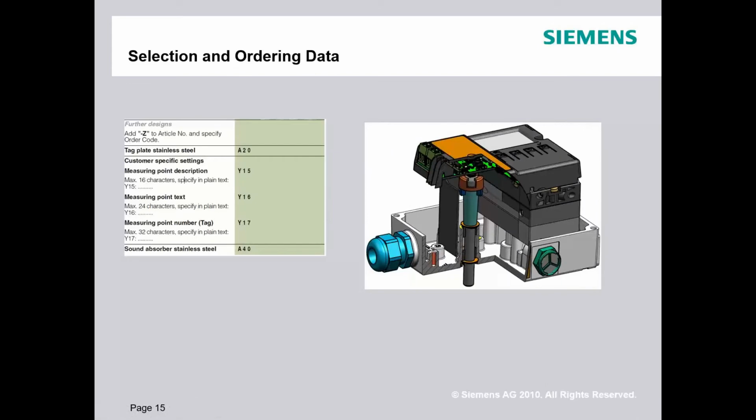Also, this is not the Hall effect. This is GMR. Most of the magnetic stuff out there, the non-contact, is a stack of magnets. It's the magnet array, and they're measuring magnetic strength. As that degrades, you have to replace those magnets. Here, we're not measuring magnetic strength. It's more of a phase shift. So what does that say? I don't ever have to replace the magnets.